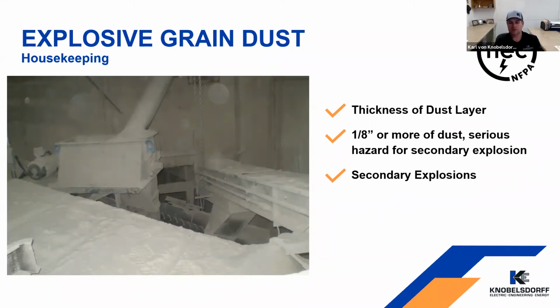It'll shake the building, it'll knock the dust off the beams, off all the equipment. And once that dust is airborne, it's the secondary explosion that then usually blows the roof or the building apart and causes serious damage. So good housekeeping is one of our best ways to keep a facility safe and not risk secondary explosions. So when we come in and do a classification for a facility, we're looking at layers of